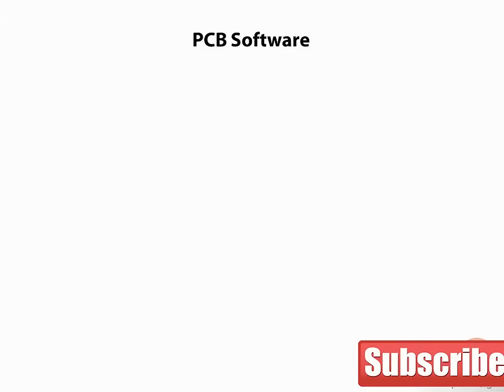PCB software packages have a number of common features. Being able to lay out a schematic is very handy. Some of the schematic examples in this course have been done with a PCB software package using the schematic feature. The neat thing about entering the schematic is that the software package begins to build the board layout in the background as you build the schematic. Parts in the layout portion can then be repositioned and the board sized to meet physical requirements.